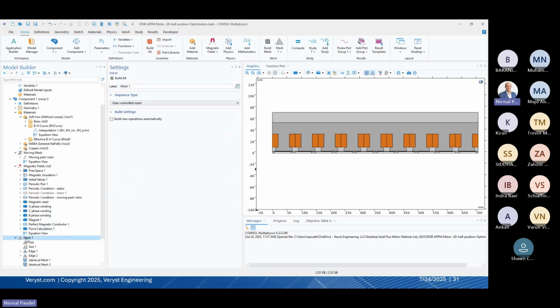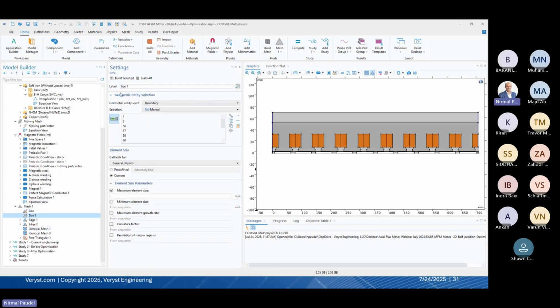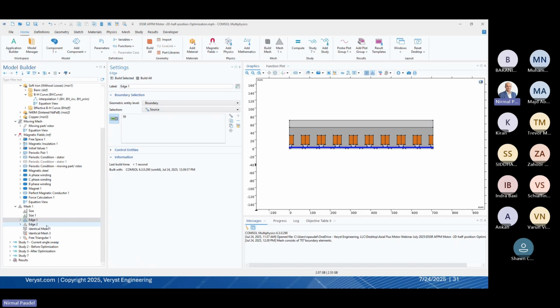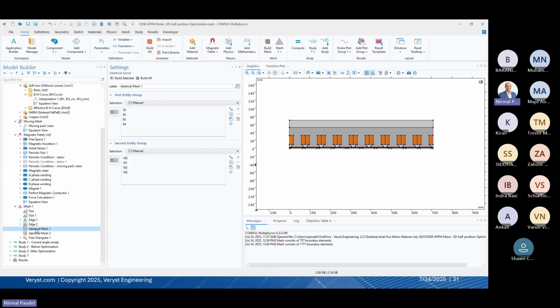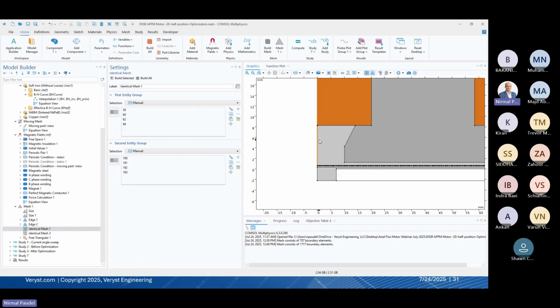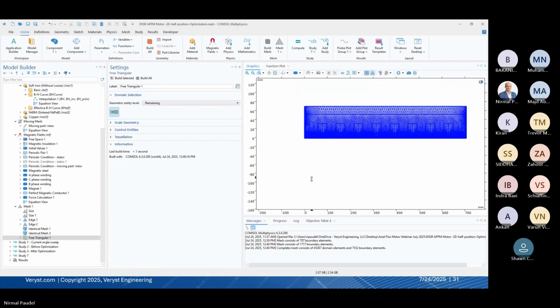So here's the mesh. We have different sizes assigned on the boundary where the periodic condition is applied. We first mesh on the edge on the identity pair on either side. And then on those periodic boundary conditions, we apply the identity mesh on either side. So finally, free triangular everywhere. This is our mesh.